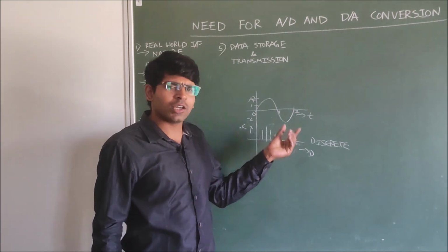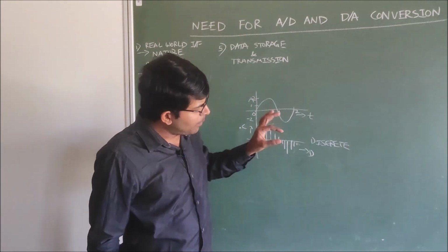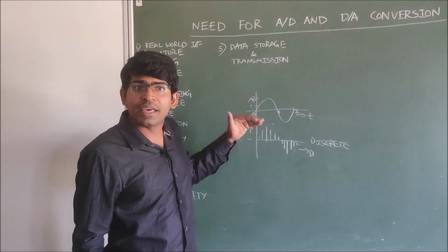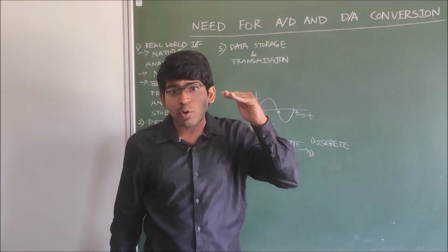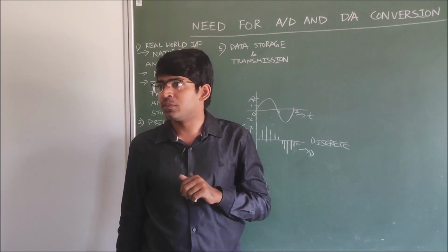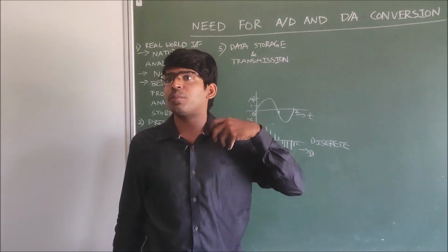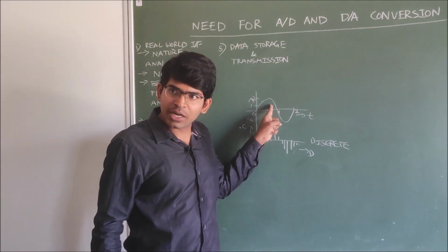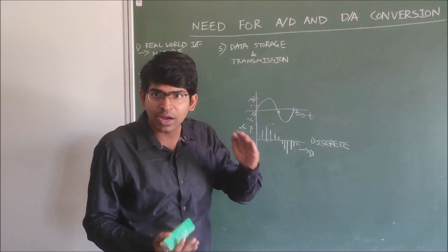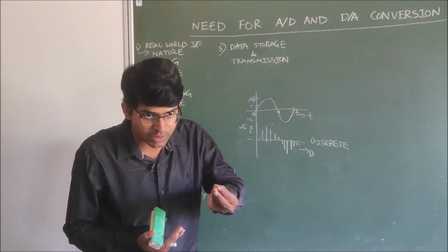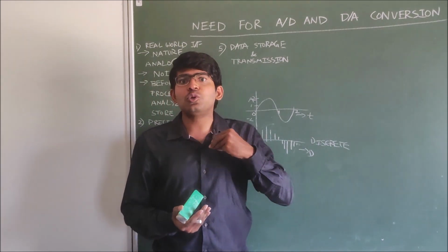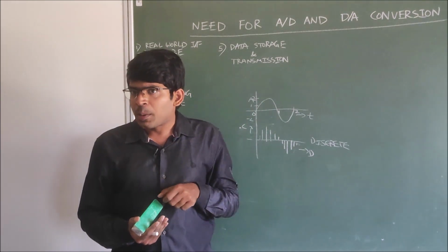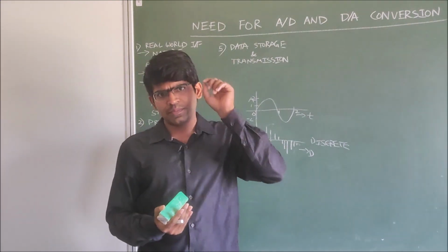There is no doubt we are sending only 12 samples, but each sample, when we send it in the voltage domain, again we have an infinite amount of information to process. Compared to the continuous or analog signal, in discrete signals we have reduced the amount of storage. We have reduced the number of samples we have to transmit. But still the problem exists.